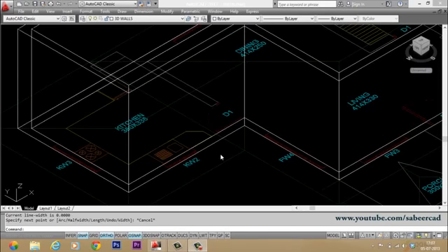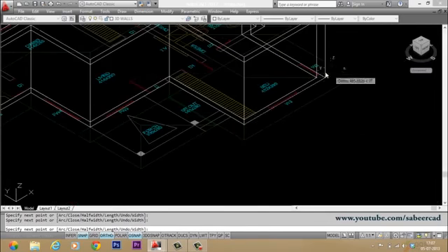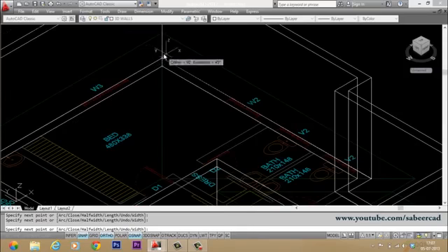Next we will create the doors and windows. But before we make these objects, we have to indicate the lintel level. You know that at the lintel level there is a beam which is running throughout, and that level is at a height of 210 centimeter, that is 7 feet from the floor level. So we will start with a polyline and I'll trace this line, that is a wall line. So I'll draw a line throughout. And I'll come back to this point and I'll give close.